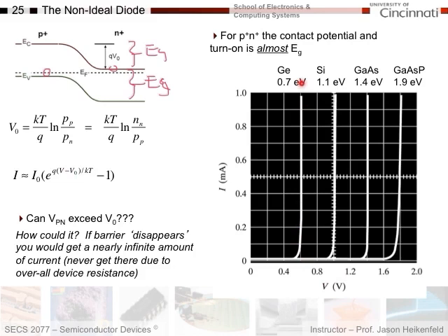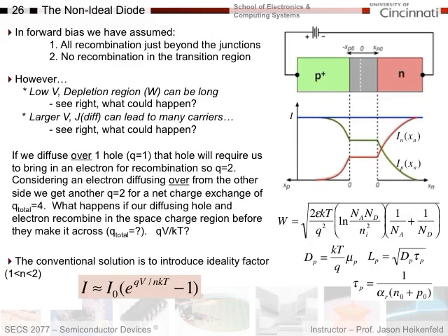Okay, so if you have a diode which has a contact potential of 0.7 volts, you're not going to apply 4 volts across that and get 4 volts across the junction itself. If you see 4 volts, then you have 4 volts that's dropping across the wires and the semiconductor material. It's not dropped across the junction because the junction has just disappeared. It passes so much current. Okay, so let's keep going forward.